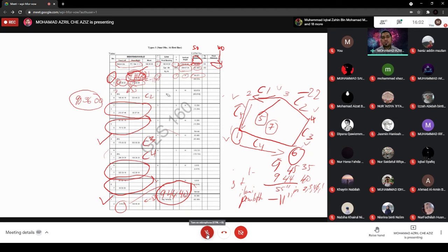Okay, that's right. Only that here, this one involves the sun observation. So after this we will have the M correction. So the M correction comes later, we don't go into it yet. So you cannot calculate the final bearing yet, because in this form you will have another value. Okay, M correction. You will apply the M correction to all lines because it will correct your orientation of a traverse network.